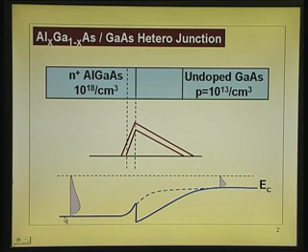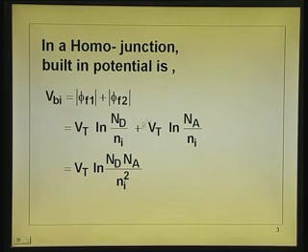and as a result you have got the conduction band edge going up like this. This is across the depletion layer, and then there is a notch which we have discussed already, discontinuity in the conduction band equal to delta E c, then there is band bending up to the edge of the depletion layer. What I am trying to point out here is, if this were a homojunction or if the notch were not present here, the built-in potential across the junction, thermal equilibrium condition, is VBI, which actually is given by this formula, Vt log Nd by Ni.